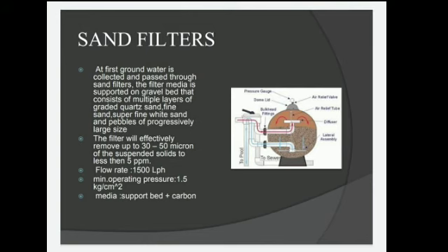The filter will effectively remove 30 to 50 micron suspended solids to less than 5 ppm. Flow rate, 1500 lph min. Operating pressure, 1.5 kilograms per square centimeter. Media, support bed plus carbon.